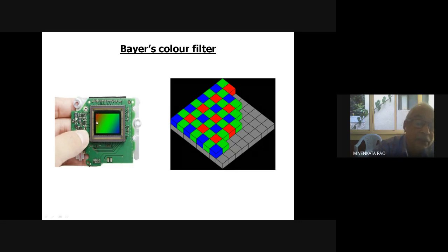The technology behind this is that on each CCD array sensor, they deposit a filter, like this. This is the combination of red, green, and blue. Each covers 1 pixel in the detector below. So light will pass through this, and then you will get the output.